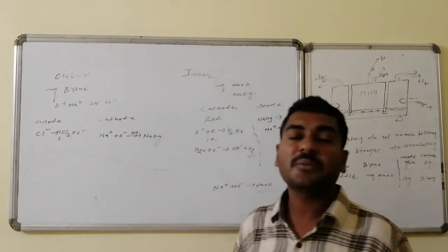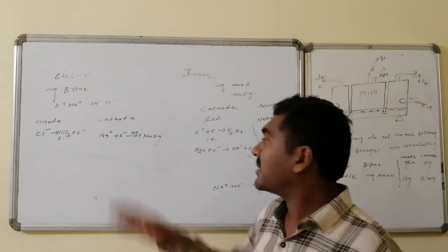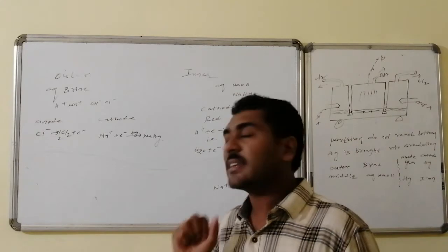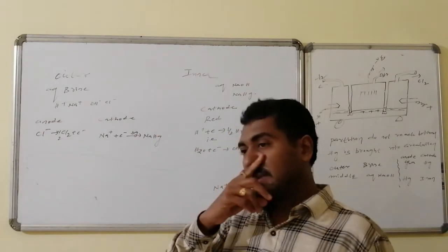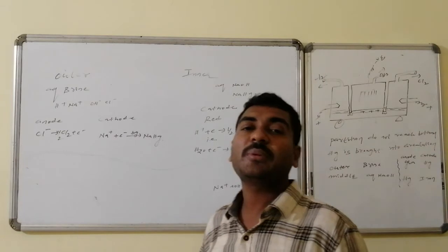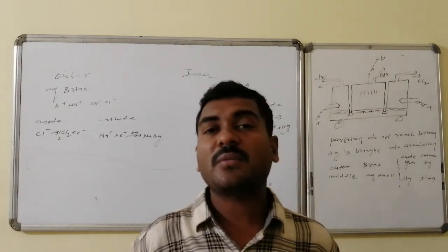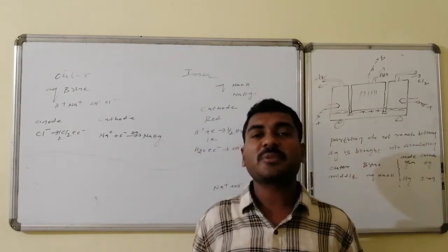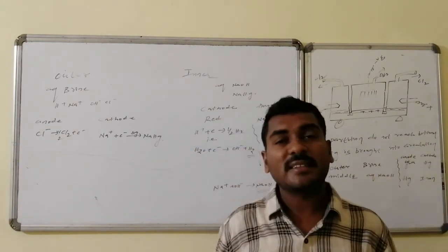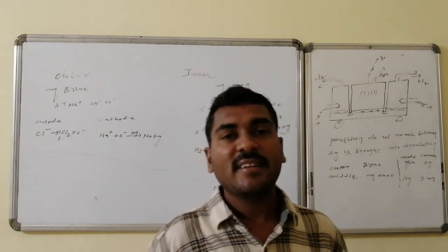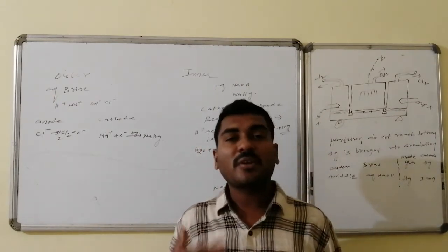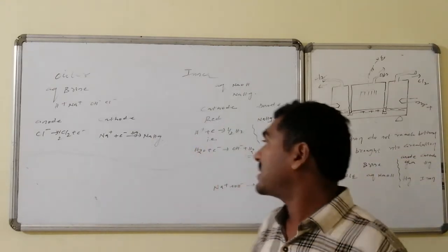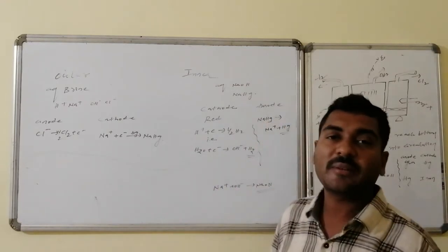Cl- is converted to chlorine, followed by liberation of an electron. That chlorine is expected to be liberated through a proper channel adjusted in the cell. Whereas at the cathode, Na+ and H+ are in competition. Though the discharge potential is higher for H+, because mercury forms an alloy, an amalgam, the Na+ after taking an electron combines with mercury, leading to the formation of sodium amalgam.